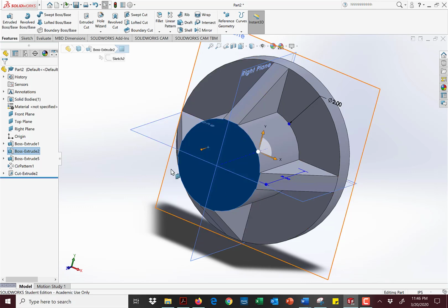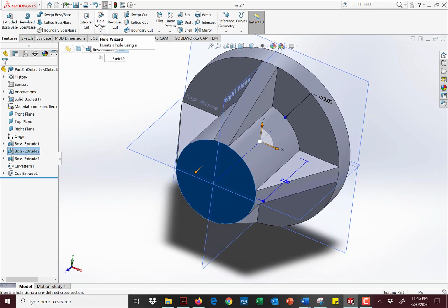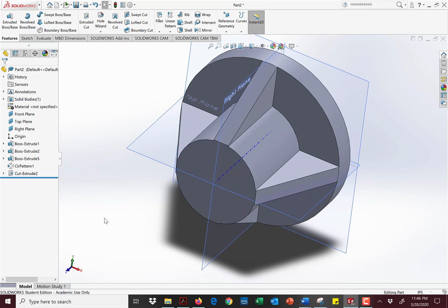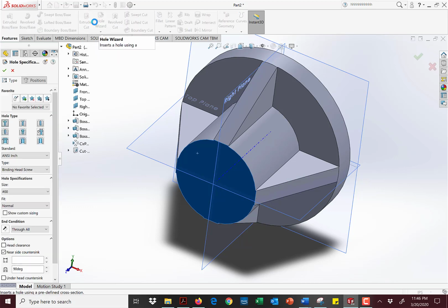It's too many steps to get it done correctly if I pick hole wizard first and then go to the face. So again, when you want to use the hole wizard, pick the face that you plan to drill the hole through. Then pick Hole Wizard. Okay? Just my advice. Next, as you look at the different options, I would recommend the standard through hole.